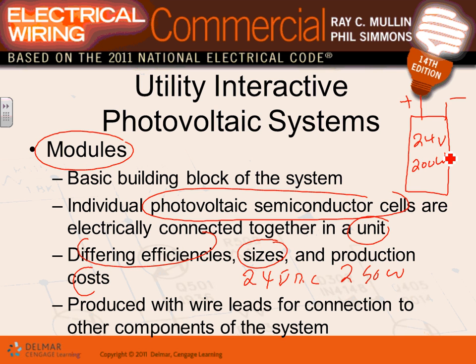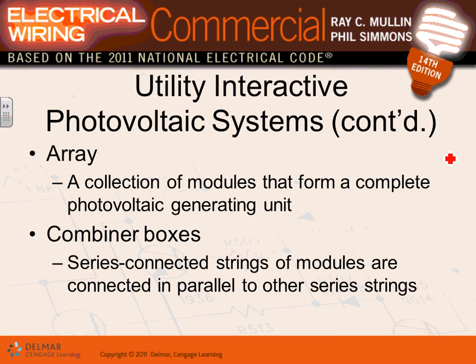You are looking at this module connected. So why do we have two wires coming out of it, one positive, one negative? So you can tie them in series to get more voltage, or in parallel to get more current. Any comments, guys, about the modules? That's the panel. If anybody's interested, Derek or Karen, we have a class that we're offering on solar photovoltaic systems, how to wire them and troubleshoot them in electrical construction.